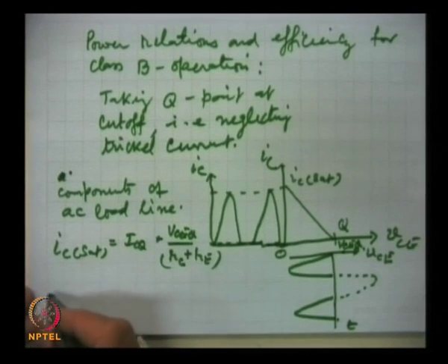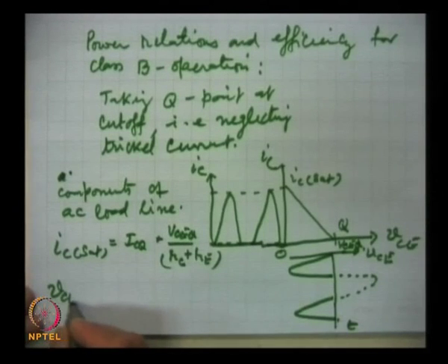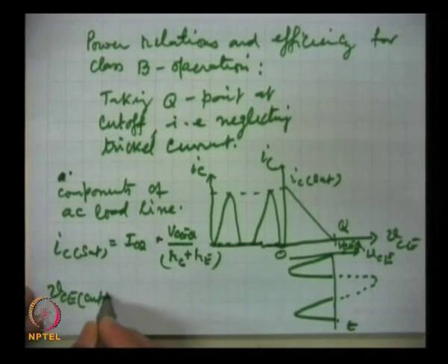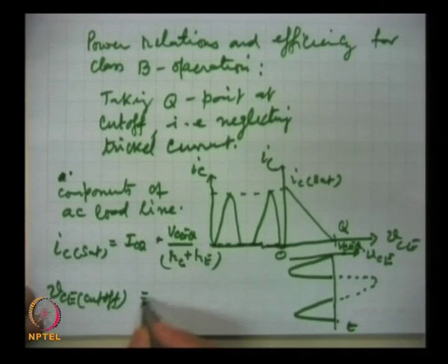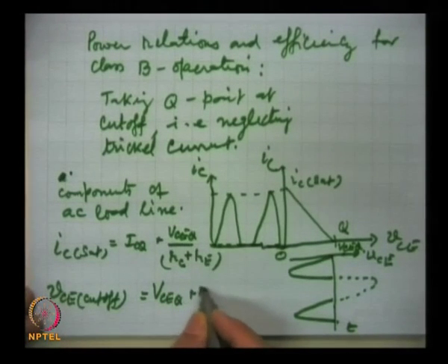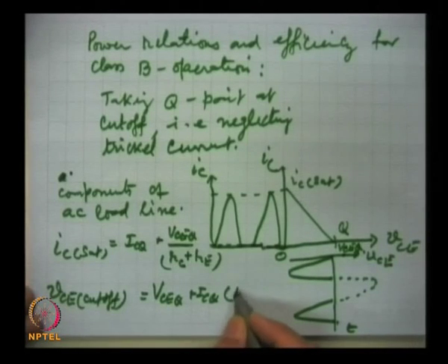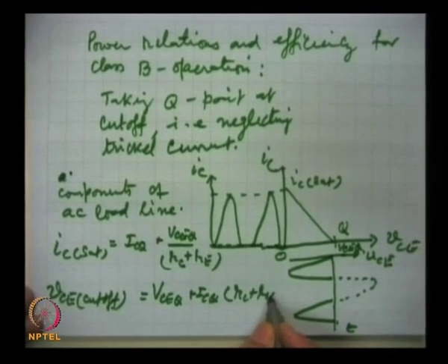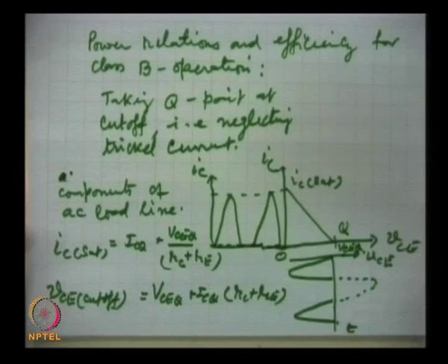And similarly, we got VCE at cutoff equal to VCEQ plus ICQ into RC plus RE. These two equations we got when we were talking about the AC load line.